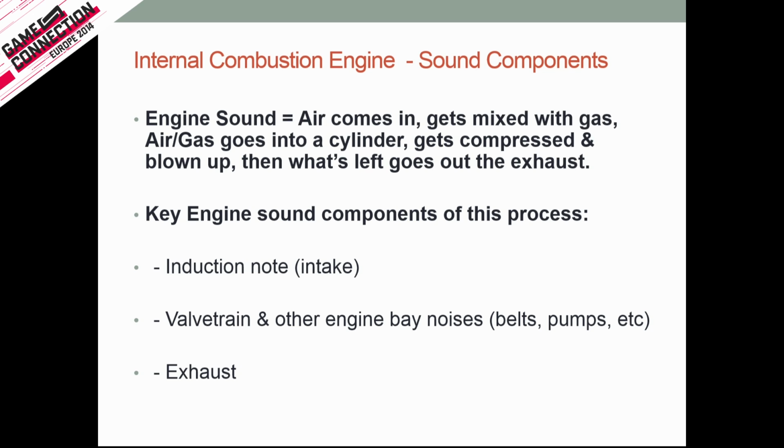So when they say a four-stroke engine, that's what they mean. Stroke one is when the piston in the cylinder comes down and sucks in the fuel-air mixture. Stroke two is compression, where it pushes up to the top of the cylinder and compresses it, making that mixture very volatile. Stroke three is the power stroke, where the spark plug lights off at the top of the cylinder and boom, blows that mixture up, which drives that piston down. And then you have the exhaust stroke, where the piston comes back up and pushes all those unspent gases down the exhaust pipe. So that's a four-stroke engine: intake, compression, power, and exhaust.